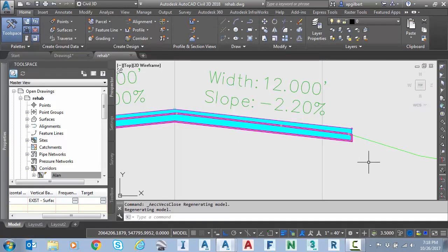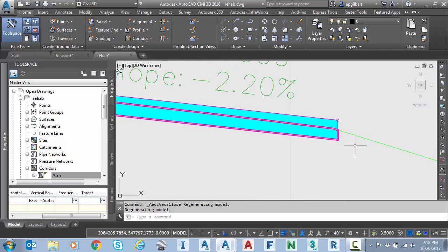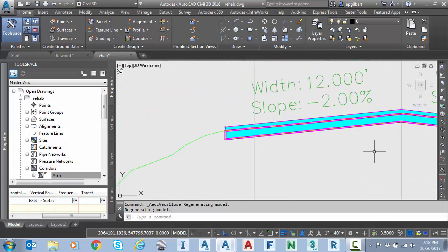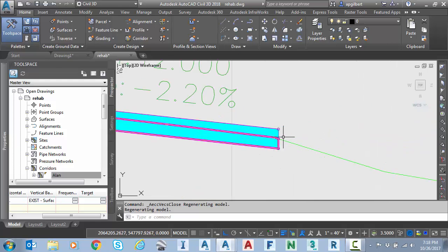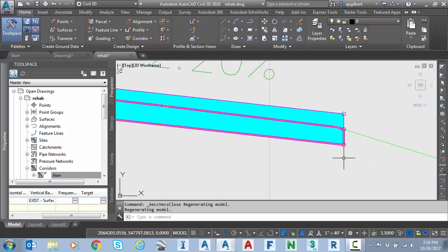So you can see I have my milling shape in dark magenta bolded, and so my minimum 1-inch mill is down here near this side, and of course I have more milling as I go across to the left. That's the critical point on this low right side. You could argue maybe that I'm looking too wide. Maybe I need to back up my milling a foot or so, not to go past this point where you have a break. What's nice about these tools is I can see that quickly and make that adjustment. But let's leave it as is for now. It makes a nice visual.